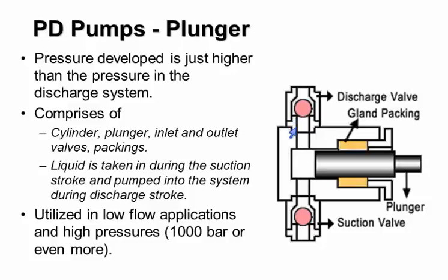These parts that I'm pointing to now are the valve seats. So there's a seat here and a seat right here. Now, if my plunger was moving left to right, in other words, I'm actually bringing the plunger back and creating a low pressure in here, what will happen to this ball here? What will happen to the ball if I create a low pressure in here? If I pull this plunger back, create a low pressure in there, what will happen to that ball there, the suction valve?